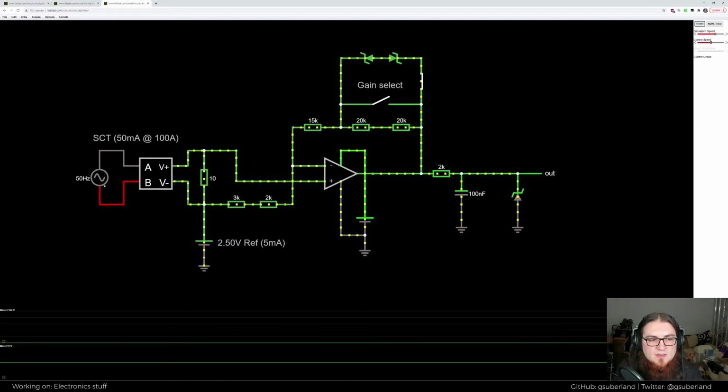Now if I just hit reset on this, I can see that it comes only up to 4.366 volts. So this Zener diode, this leakage current generated by this sort of model here, the Zener diodes aren't really here. This is just modeling the leakage current of the analog switch IC. And we can see that this is 4.366 volts instead of the original voltage, which was